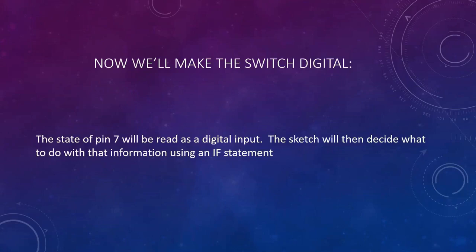But now all we'd have to do is change one line of code somewhere, and now when the input pin reads that the switch is disconnected or tilted, then we would tell pin 13 to go make the buzzer and the light go crazy. That would be a kind of tilt or movement alarm. So let's see how that would look.